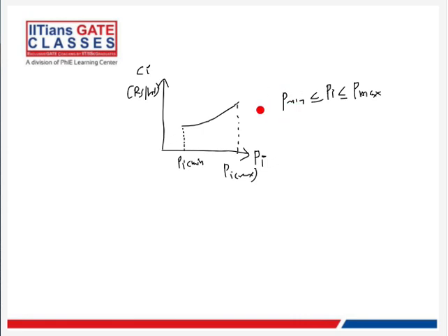So why do we have P min? Why is it not going all the way to zero? An ideal condition would be between 0 and P max. It is not so because boilers are required to maintain a minimum temperature, otherwise it will lead to boiler instability. Even with hydro and nuclear power plants, there will be a minimum power generation that we need to maintain for the system to physically operate correctly. And what is P max? P max is the generator's maximum rating, usually S max.